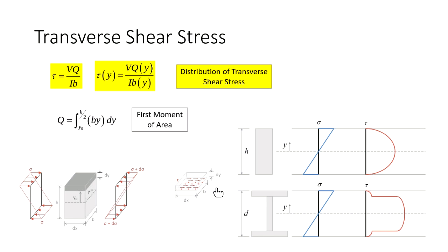Okay. Now, if you look at the stress profile of various beams, and this is the image here on the bottom right, what you find is that the bending stress profile doesn't really change, but this is the shear stress profile. So this would kind of be what the shear stress profile looks like for a rectangular section. And this would be what the shear stress profile looks like for an I-beam. And so with both cases, you get your maximum shear stress in the middle.